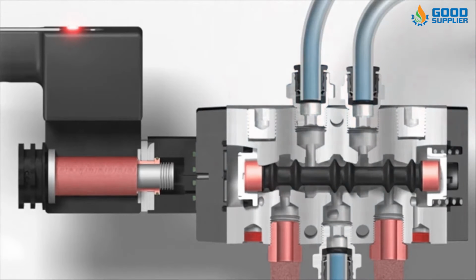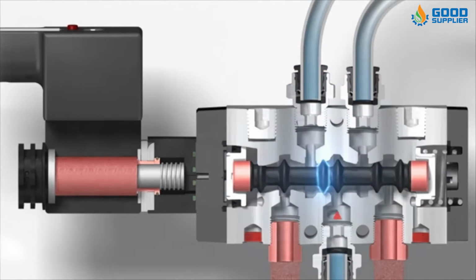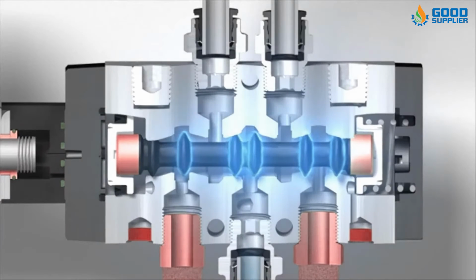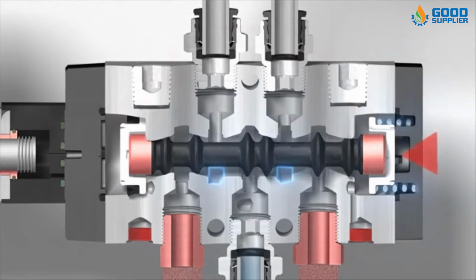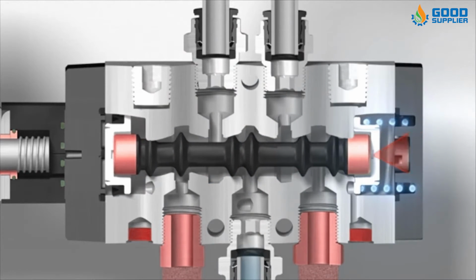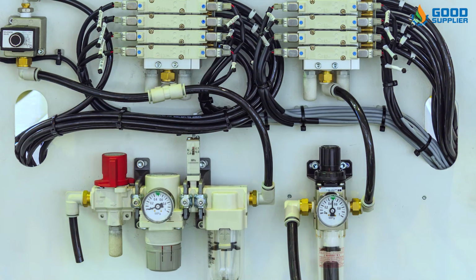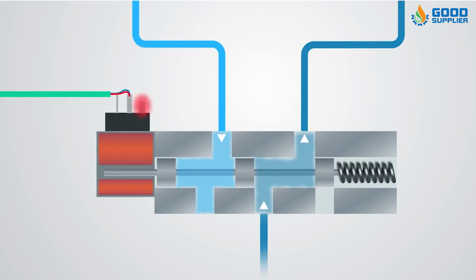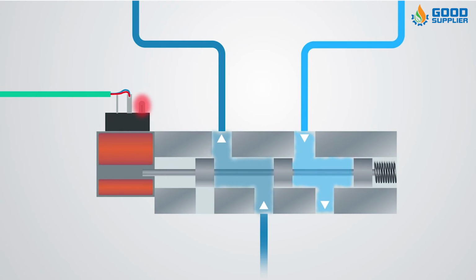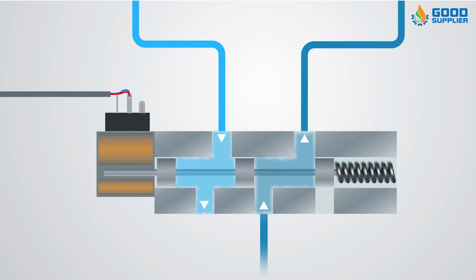The spring offset pneumatic valves refer to how airflow direction is switched. For example, in a 2-way directional valve, the valve is either open, airflow is enabled, or closed, airflow is prevented. For each port to assume an open or closed position, an actuator moves a valve spool into position. To release the valve spool and return the pneumatic valve to its previous position, a spring releases the spool. A 2-way directional valve that functions in this manner is also called a spring offset valve.